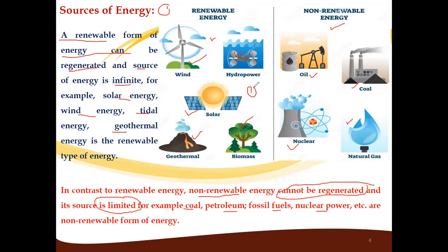A solar panel usually consists of a glass faced, sealed, insulated box with a black matte interior finish. Inside there are coils full of a heat collecting medium such as water. The sun heats the water in the coil, which is pumped through a heat transfer tank containing water. The water in the tank is heated and then either stored or pumped through the building to heat rooms.